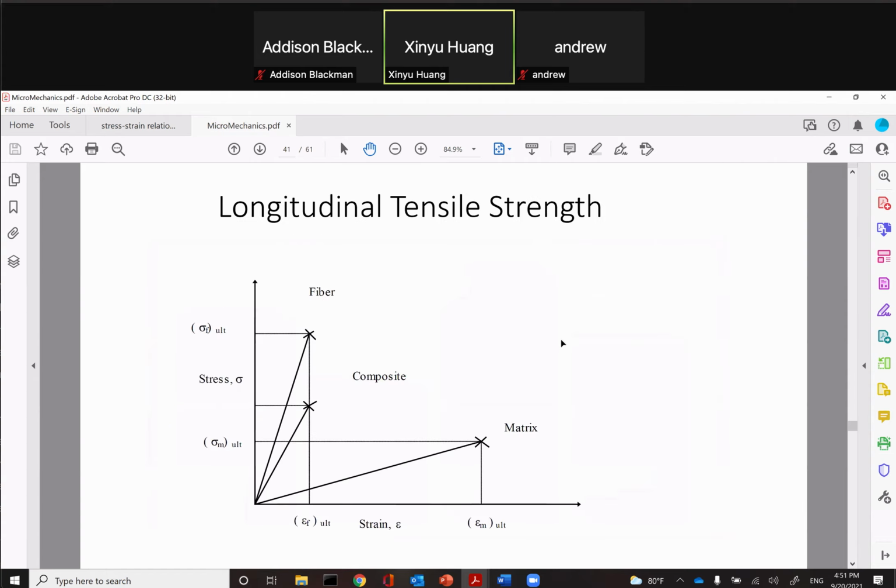All right. So this is a pretty close picture. If you look at the stress strain curve of material failure behavior, the fiber is usually very brittle, doesn't yield. You just go up linearly to a point, and boom, it breaks. Matrix depends on what matrix. Matrix sometimes yields a little bit, but there are also brittle matrices.